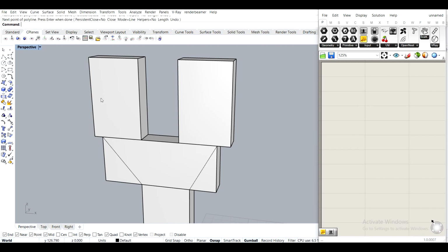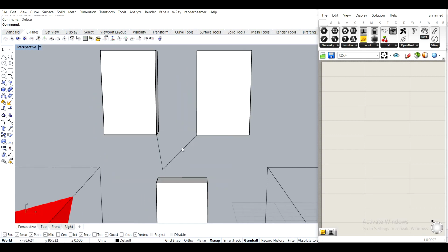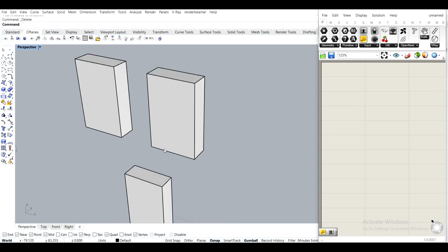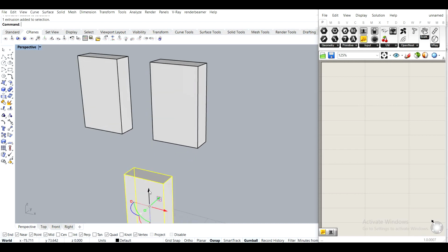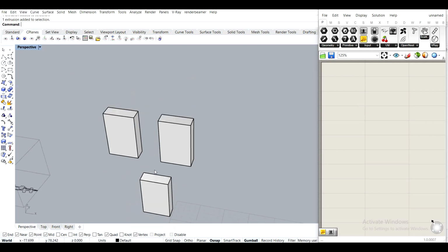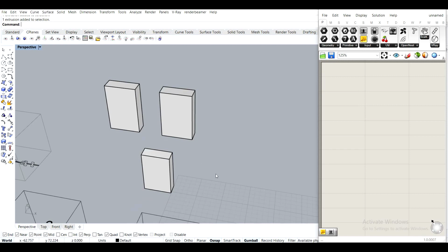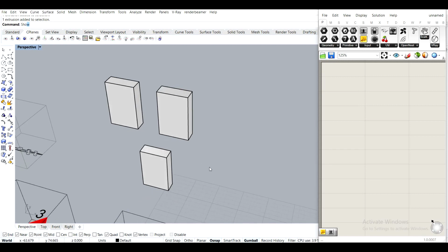So you start cutting those away. Instead of doing that manually, you can use Grasshopper to optimize it and to generate a form that has the smallest amount of volume possible while still being able to hold these two elements, basically connect the base with these two elements, right?